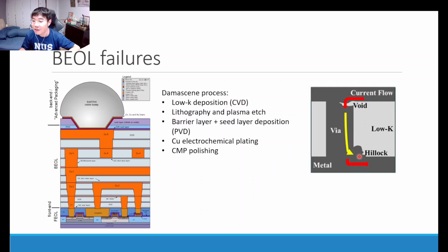In addition to void formation, we can also see the formation of hillocks. After all, if material leaves a certain area, forming a void, it needs to appear somewhere else, and where it appears, it will form a hillock, which is a protrusion of your metal material, and that is the one that can cause short circuits, as well as other undesirable effects.